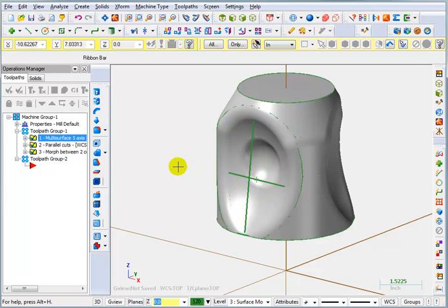So we can still use our 5-axis machine for positioning to multiple sides and then doing 3-axis machining. This is referred to as 3+2 machining, or sometimes they call it 2+3, because you're doing a 2-axis tilt of the 5-axis machine and then doing a 3-axis surface machining. Now we need to create some kind of a plane for the face that we're going to machine.